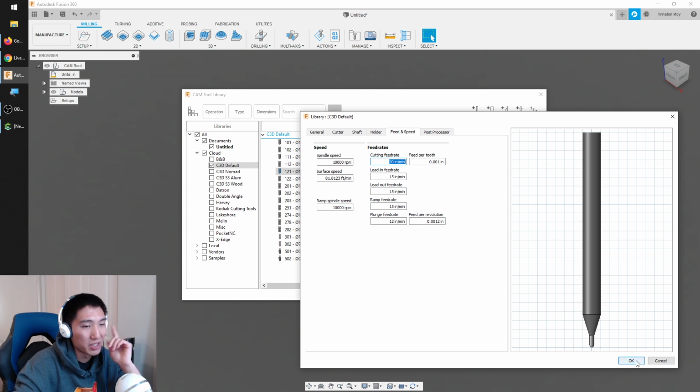Even if you just split them up, like I have a library for wood or aluminum, you're going to have to use a little bit of instinct and gut feeling for which settings to use for which toolpaths. For me, I sort of know, if I'm cutting aluminum, start at about 10 thou, 0.01 inches or quarter millimeter, and then aim for a certain chip load.